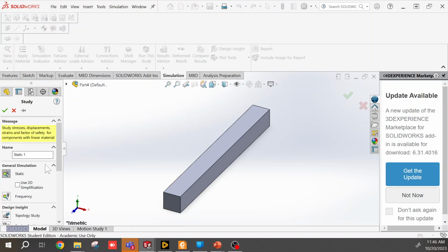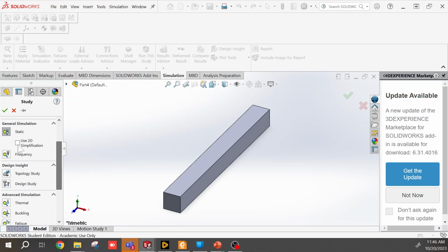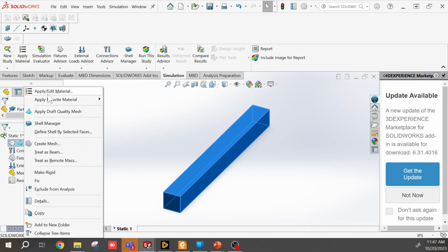You can name the study whatever you want, but here's where the options exist for all of the different types of studies. Thermal, buckling, nonlinear, fatigue, all of the things that we talked about before. But in this case, we're just going to pick a typical static study and we'll say okay. And now it's going to invoke all of the mathematical framework for a static study. And the first thing we need to do is apply a material. So we'll right click on the part.